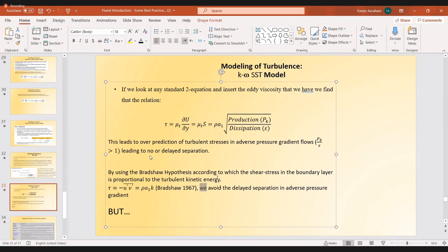So it really does work better for aerodynamic flows. That was the name of the publication, but it could be not better than, I don't know, the realizable K epsilon or the BSL for the other cases. And you can change this A1.